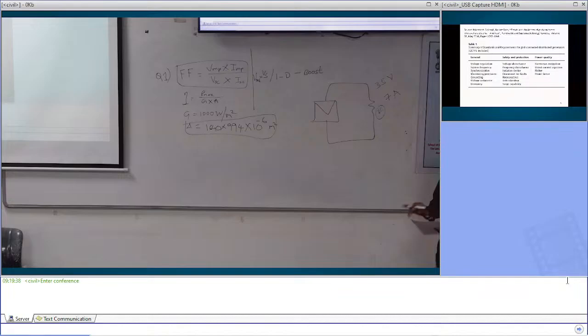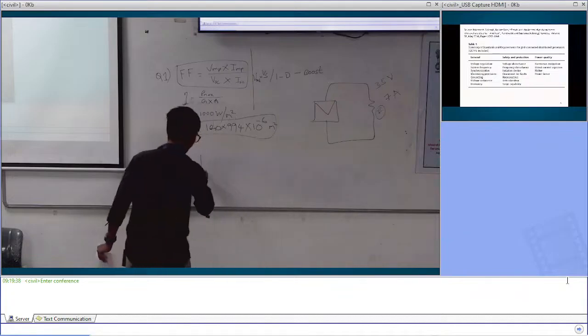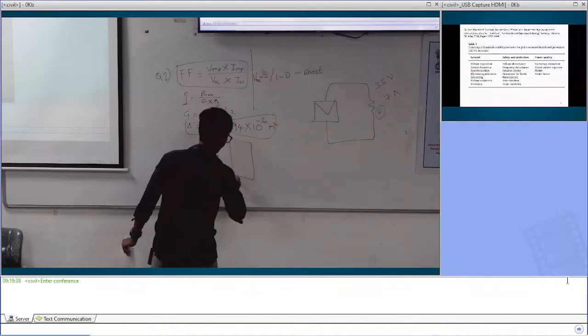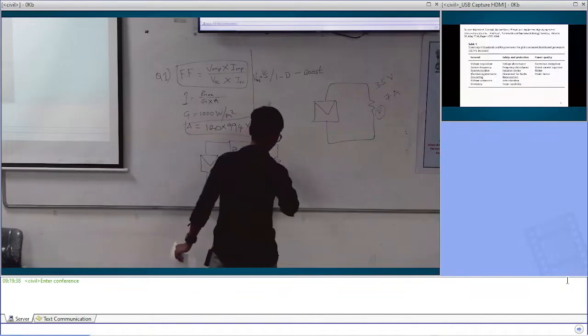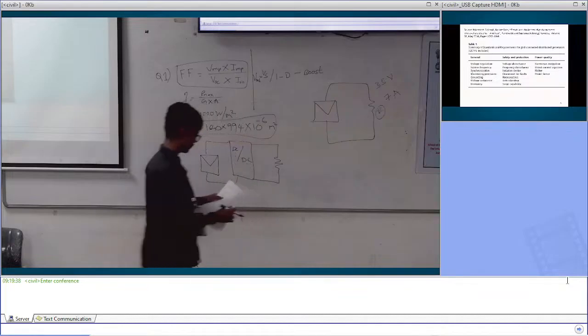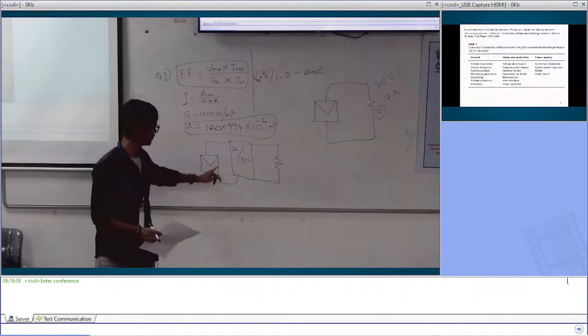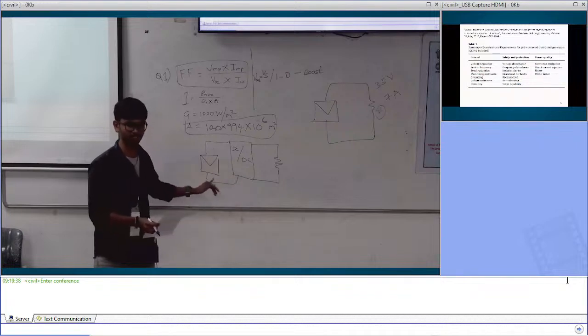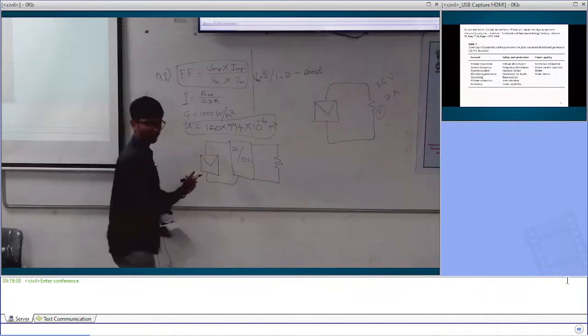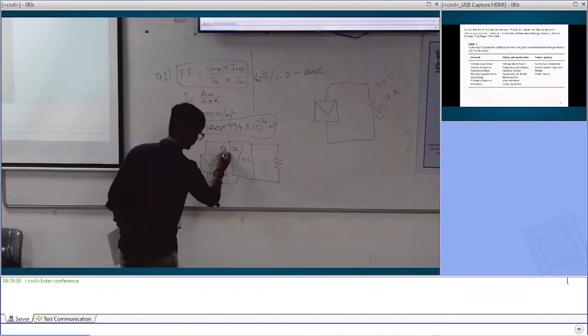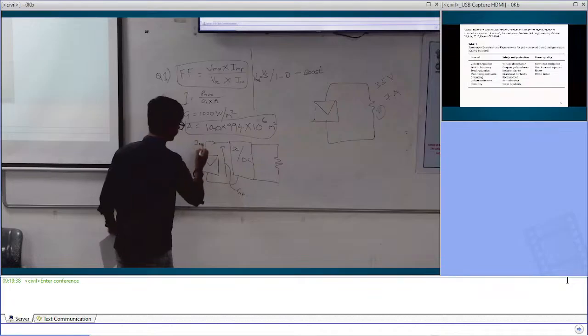Now we are telling that a boost converter is connected in between the panel and the same resistor. Now a boost converter is connected with the PV panel such that the PV panel is working at MPPT. That means we are extracting maximum power from the PV, that is this voltage as VMP and this current as IMP.